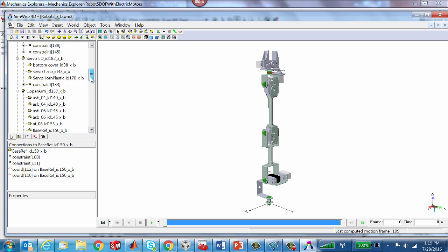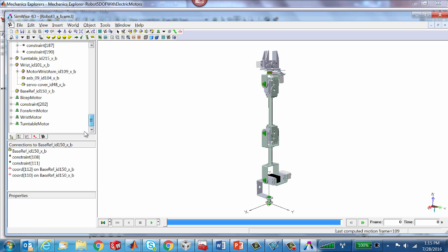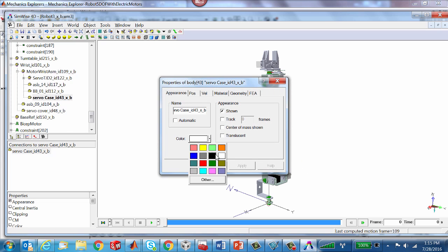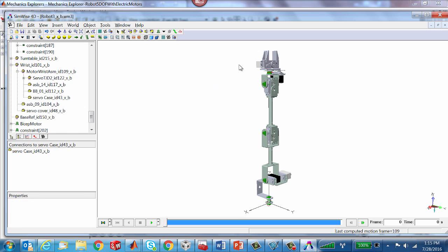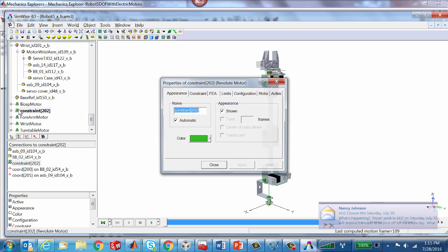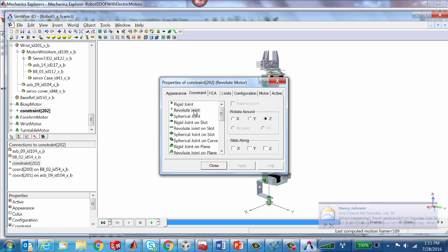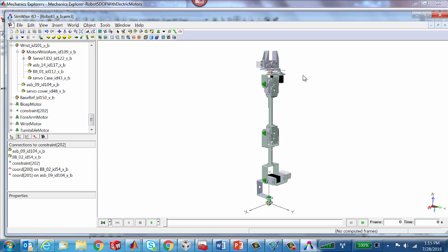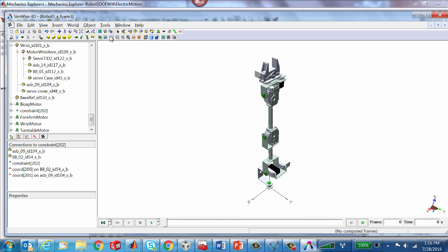Okay. All right. And now I'm going to correct a mistake I just made. This really is not going to be a motor. You actually can see that there's no black motor lined up with it. There's actually a motor right there. Let's go to properties and make that black. Okay. And then let's go fix the one that we just did. All right, and so instead of this being a motor, this is simply going to be a constraint. It's going to be a passive hinge that we use the term Revolute joint for. All right, and the motor actuation really occurs through some gears.